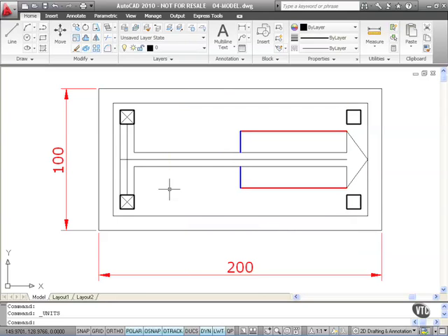So I know that everything here is metric and in millimeters, and that's what I'm going to work with. But AutoCAD won't tell me that. It just assumes 100 units, metric, 200 units, metric. I have to work around that and make sure that everything else is consistent. So when working in the Model tab, you have to make sure that you're working full size and, more importantly, to the appropriate units that you want to work to in AutoCAD.